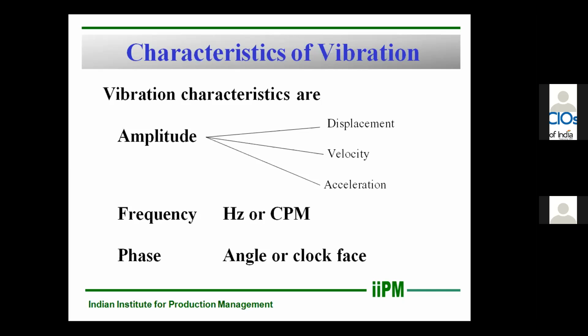Then we have phase. Phase will identify how the shaft is moving inside the bearing housing. So phase will give a confirmation. Because in vibration analysis, many problems have a similar pattern. You will have a similar pattern for unbalance and for misalignment, the same type of spectrum will be generated. So how could you identify? You can identify by using phase.